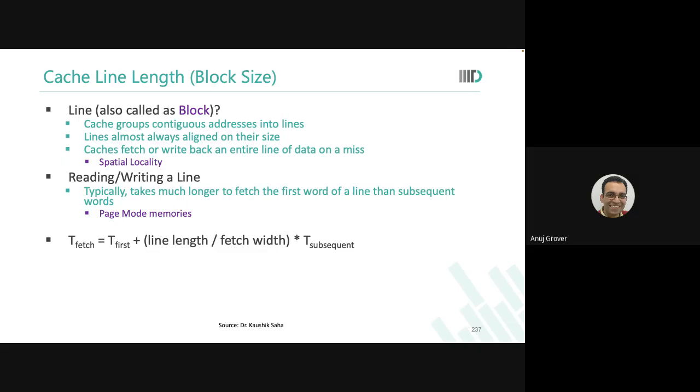Because first, you will have to make that many IO pads and that many pins. That is manufacturing cost. But also, when you need to solder, you will need to solder as many pins. So even at the time of assembly, it's higher cost. So there could be applications which want a minimum number of pins, therefore very high speed transfer may not be possible. If performance is not a premium, then you could do that.